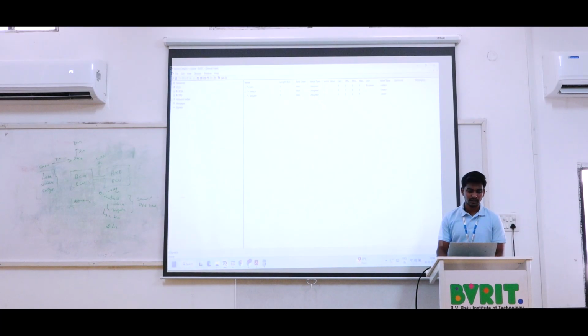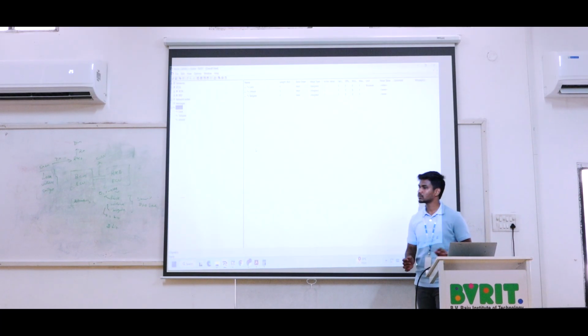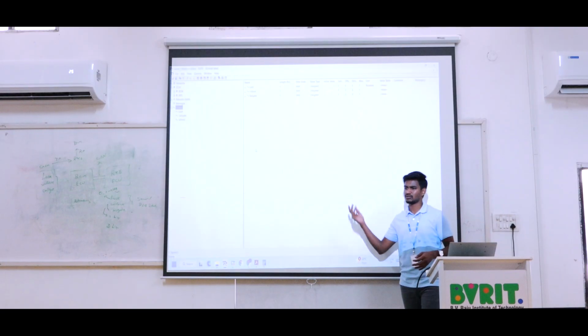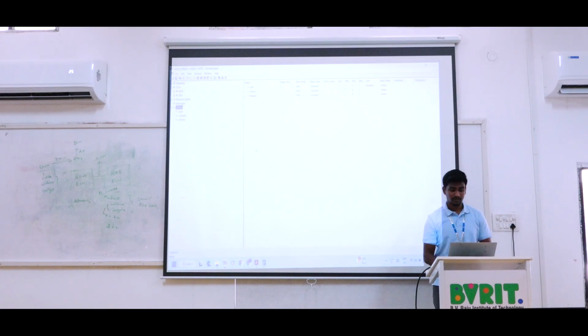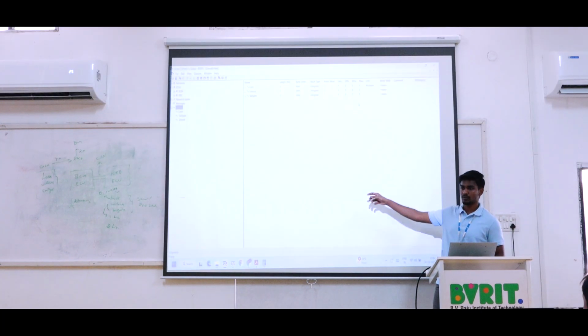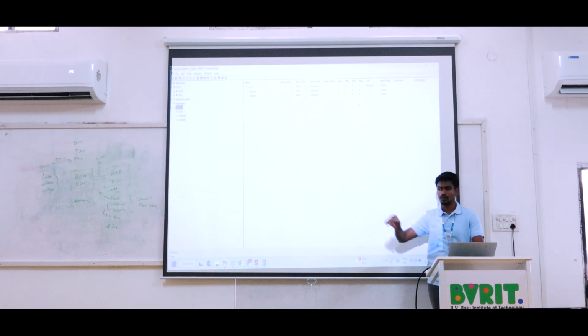So now we have created the three signals. If you don't provide anything for the unit value, there is not an issue. The mandatory things here are the minimum, maximum value, factor and then offset also. I will explain the offset with one more signal value. Here there is no need of offset.